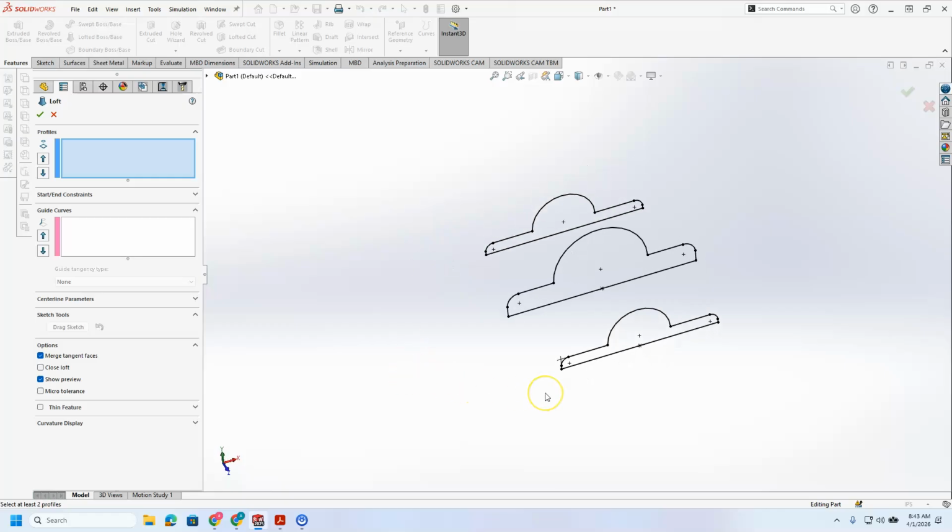The other thing that it wants you to pick that it doesn't tell you is it wants you to try and pick approximately the same point on all 3. It's going to guide the loft along your selected points. Another thing is we want to pick points where there's already going to be a visible edge of the part, because the points we select are always going to generate a visible edge. So we want to hide that in an edge that's already going to be a visible edge.